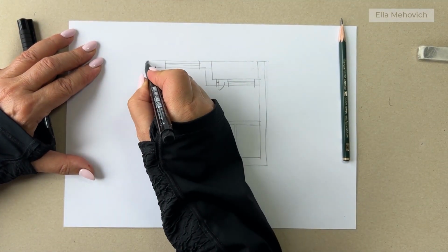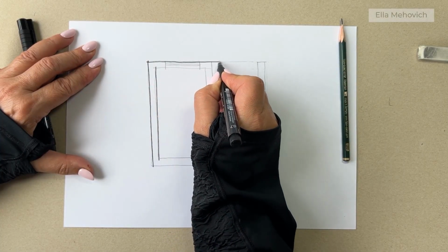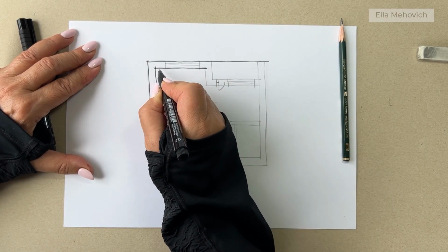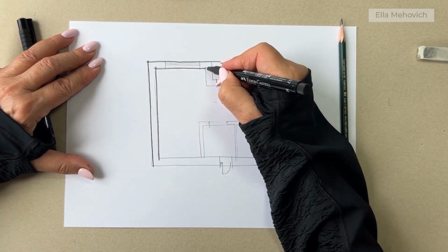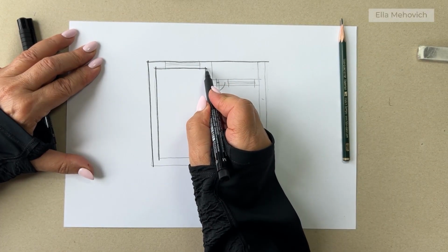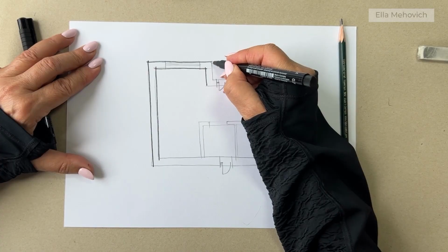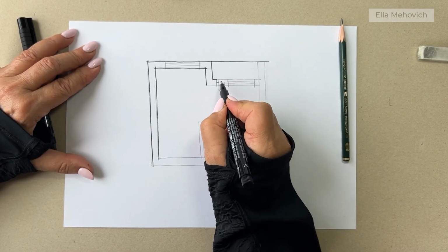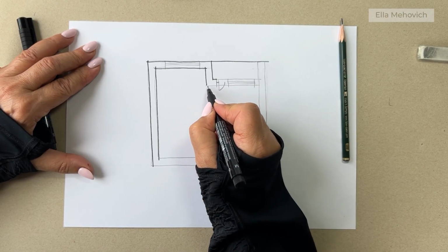We try to draw the lines in one breath, that is, without stopping, from one point to another, from one corner to another. And it's perfectly fine if we get these little tails in the corners, see? In architectural graphics, that's even considered a stylistic technique. Where we have a doorway, we don't outline it.